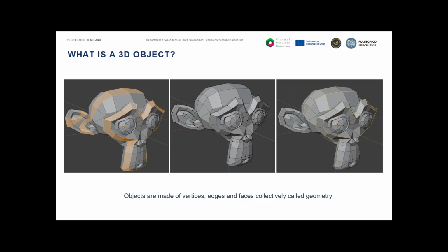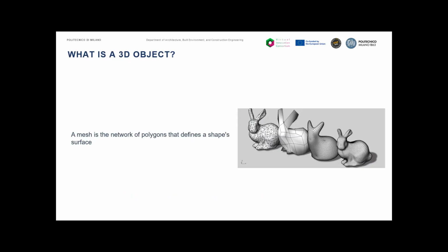This distinction matters significantly for operations like subdivision, so creating smoother surfaces, deformation, so changing the actual form of the 3D object, and UV unwrapping, so giving the 3D object an actual material. All of which depend more on how a mesh is organized in its topology than on where its vertices are. So still, what is a 3D object?